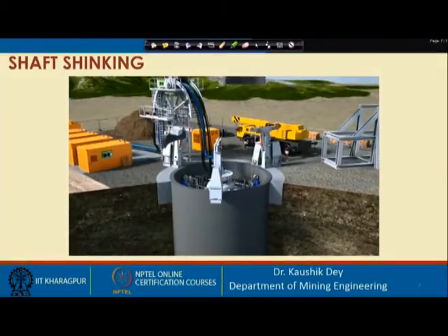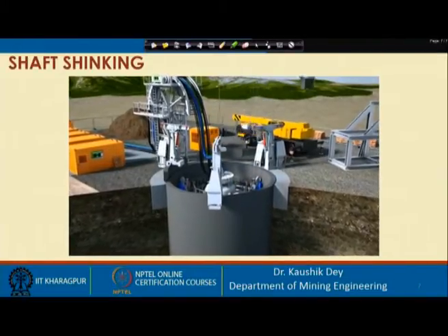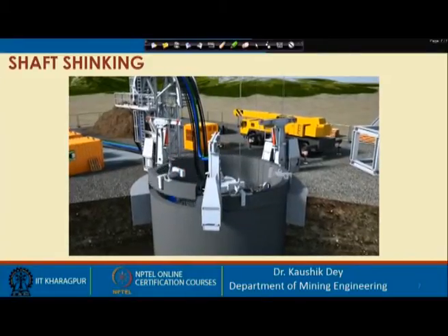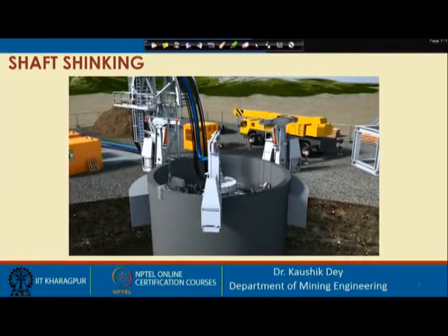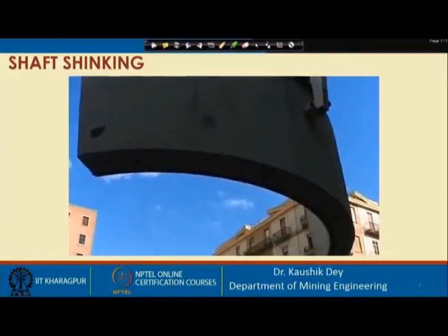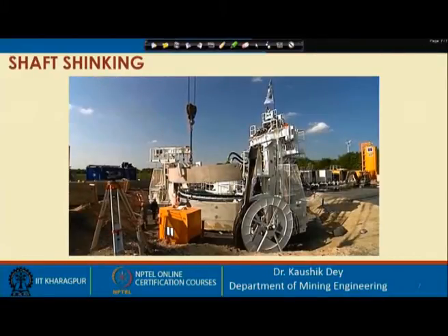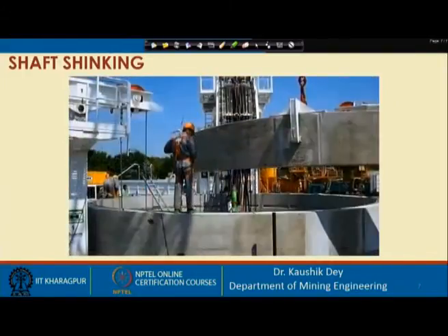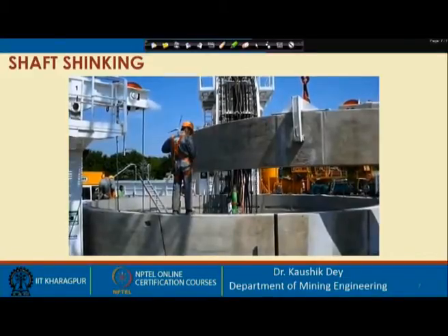As the shaft sinks lower, precast concrete segments with rubber sealing gaskets are bolted in place on the top of the shaft. So after achieving the significant depth, the heightening of the sidewalls is carried out by either precast rings or in situ concrete. Excavation, shaft sinking, and construction of the next ring can take place continuously. The molds for the segments are also supplied as part of the shaft sinking equipment package.